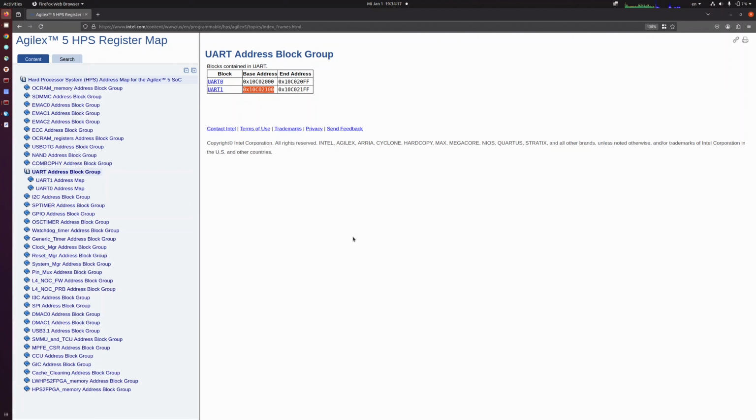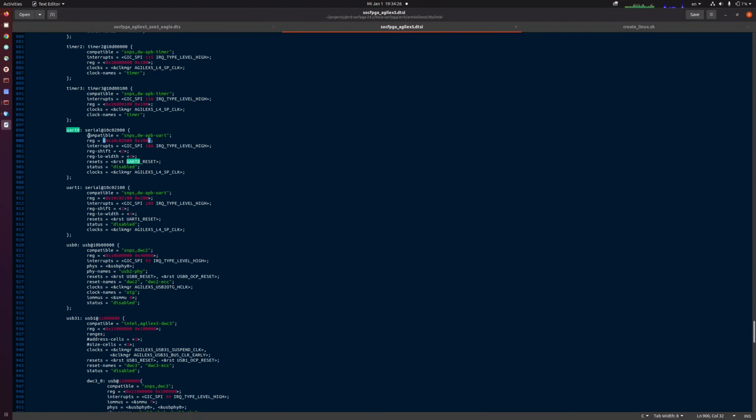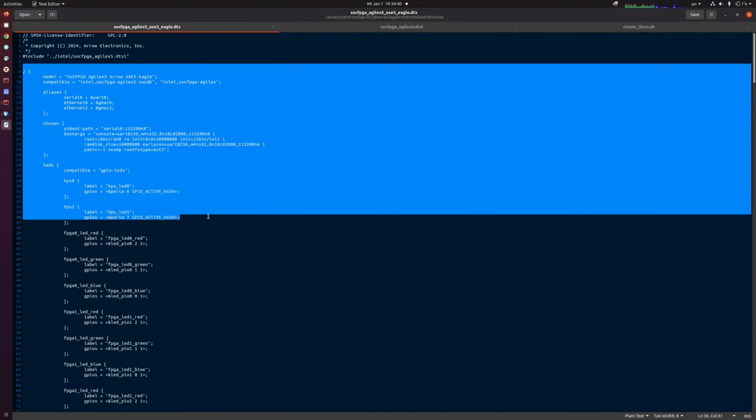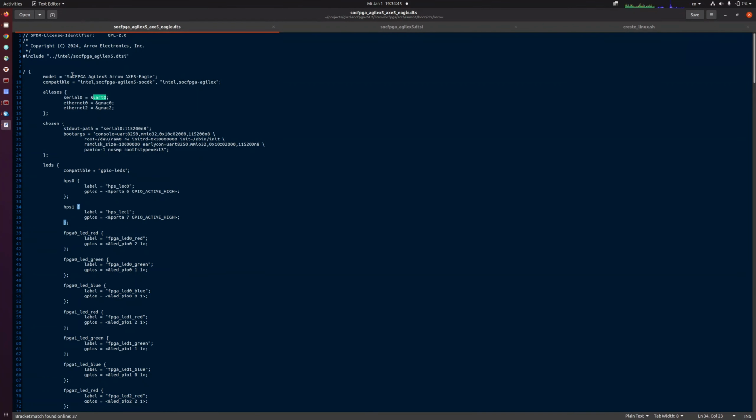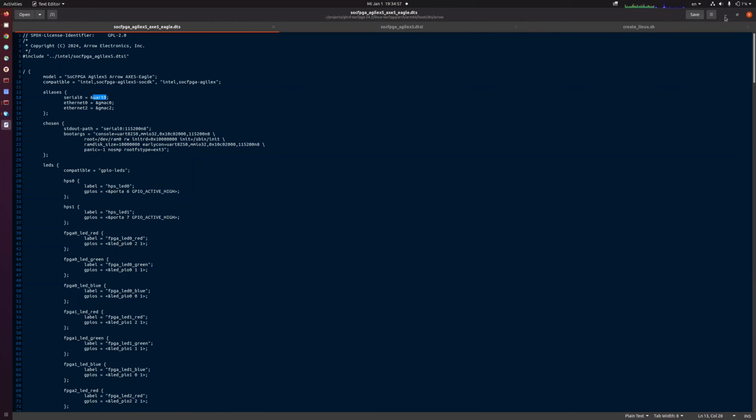And this is great. But the other method we did, through going to the Agilex5 DTSI file, is also valid, because here the addresses are also mapped, and in our Agilex5 we included this information from Intel Altera in our own DTS file. And this DTS file is for the Agilex5 board. And the configurations of the base DTSI are used here within this file.